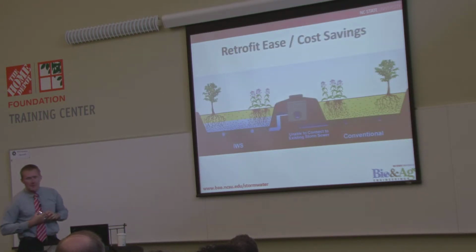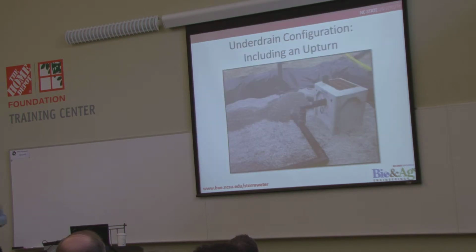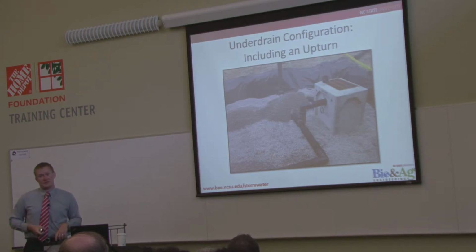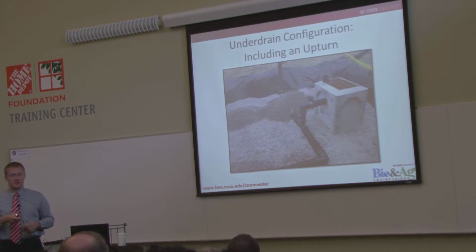That's one design consideration. On that previous slide, is that at the end of the pipe for checking it? It looks like there's a stand pipe at the end. This right here? Yes, right here. That's a clean out. So you can drop a roto-rooter or a camera down to see if you've got clogging of your under drains. We've never had problems with under drains getting roots in them like you would with a sanitary sewer. So it's for maintenance purposes. Yeah, this is HDPE. I would prefer to see PVC personally, but in this case, it is HDPE.